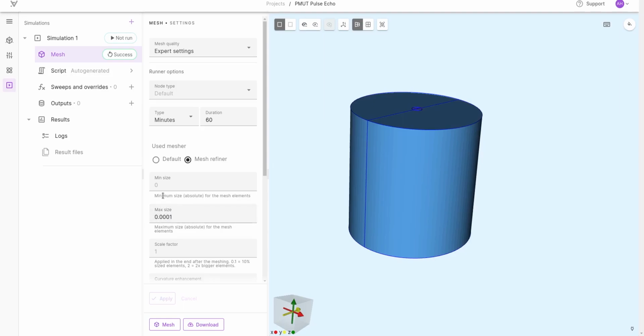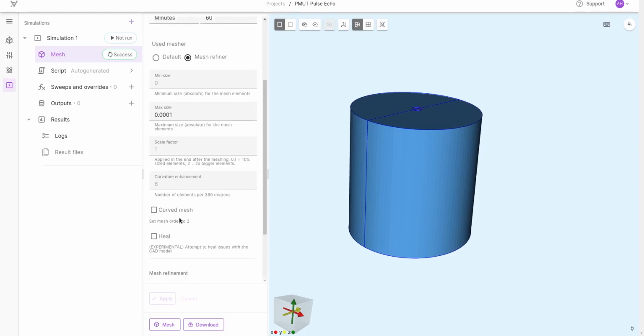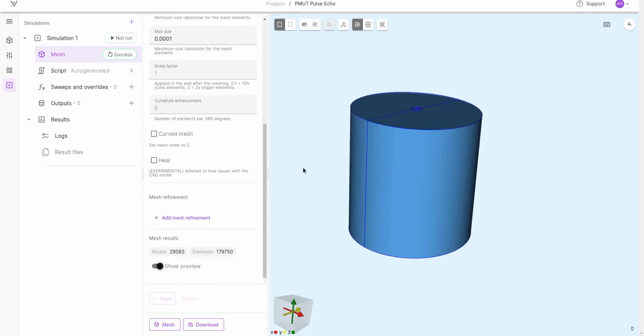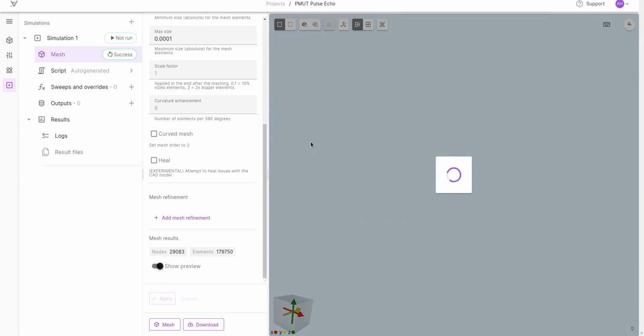Now, of course, if you put a rectangular pulse, you have an infinite number of frequencies, so you have to truncate it at some point. But here, this will capture the highest frequency of interest for us quite nicely. Definitely the 1 megahertz and a few harmonics as well.